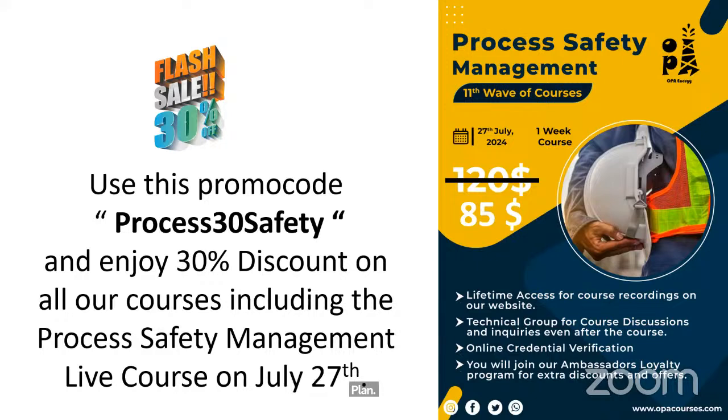But FMEA is also a risk analysis technique, but it is for a certain device, a certain process, a certain equipment, to study the failure that already happened in this equipment or process. So in FMEA, the failure already happened, and you study the failure mode in this equipment or process and make an analysis to prevent the recurrence of this failure. But HAZOP can be done before you start construction of the plant. HAZOP is after design. Once the designer sets the safe design, you start the HAZOP study to know if this design is safe to be constructed or not.